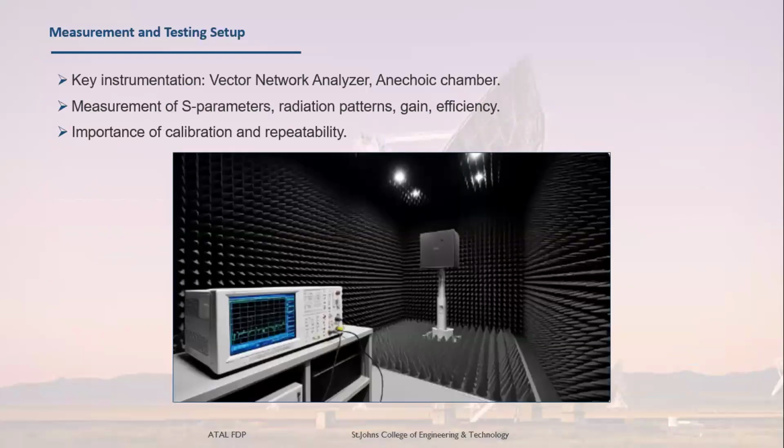Yes, this is the way I measure the radiation pattern. This is an anechoic chamber, where the reflections are completely absorbed. When I measure the radiation pattern, these absorbers will not reflect the signal back. They absorb completely. If they reflect, the performance of the antenna is affected.